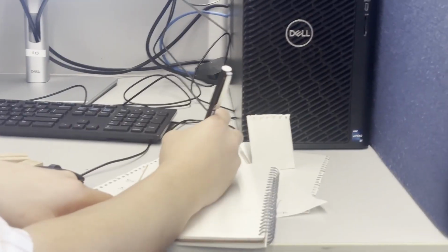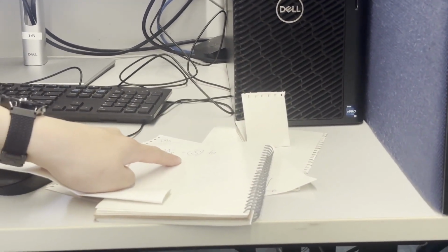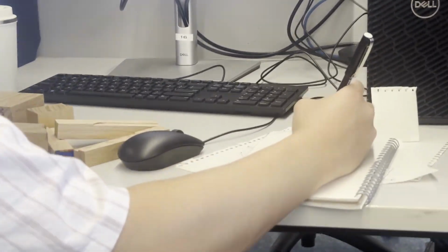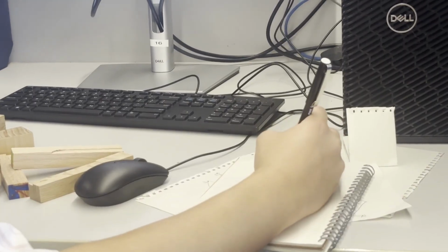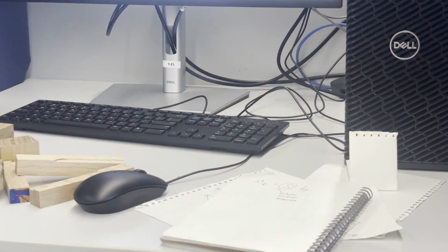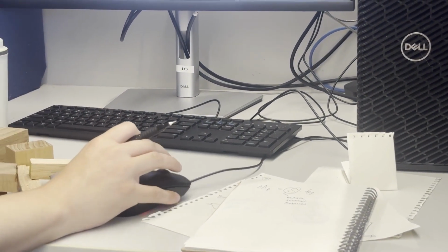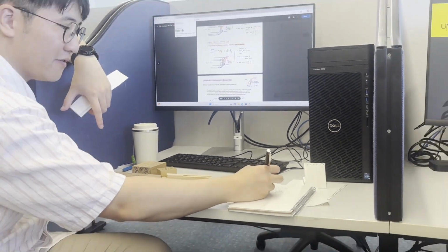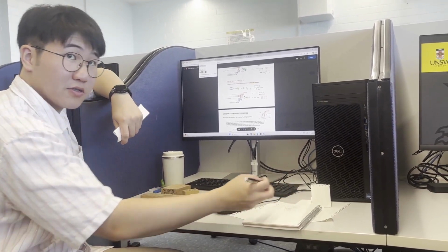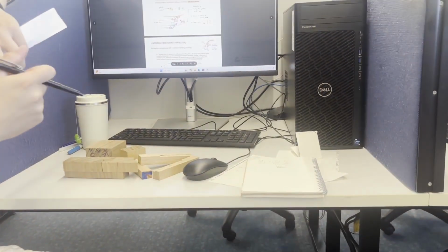For plastic bending, we have a similar thing going on, except now we're multiplying by a different quantity called S. S is the plastic section modulus. Okay. So does that make sense? It's basically the amount of bending that I can take is its material strength multiplied by these values, right? Your elastic section modulus and your plastic section modulus.